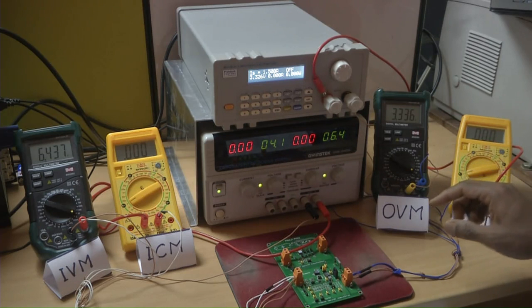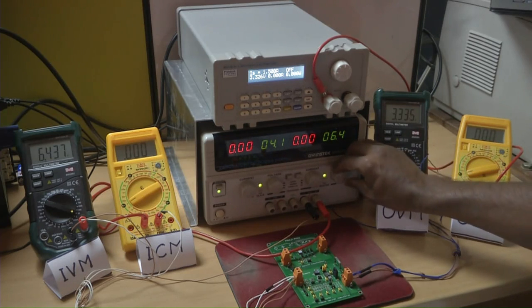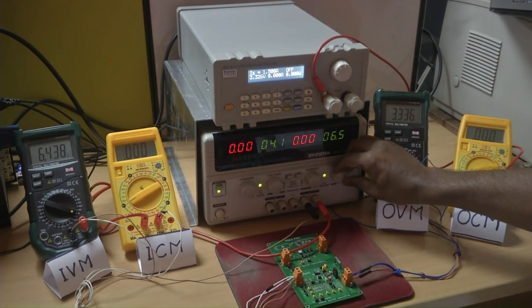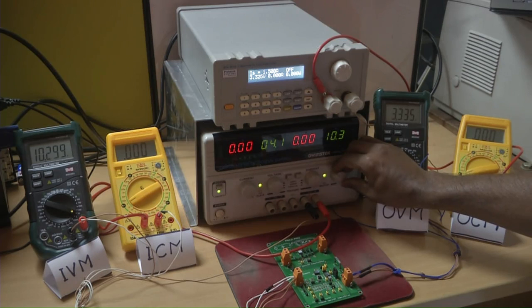Now what is very important at this stage is the switching frequency. The switching frequency under which this experiment is done is 250 kilohertz. What you can also do is repeat the whole set again for 500 kilohertz switching frequency. At the end you will end up with a nice table, and from there you can actually make out what is actually happening.